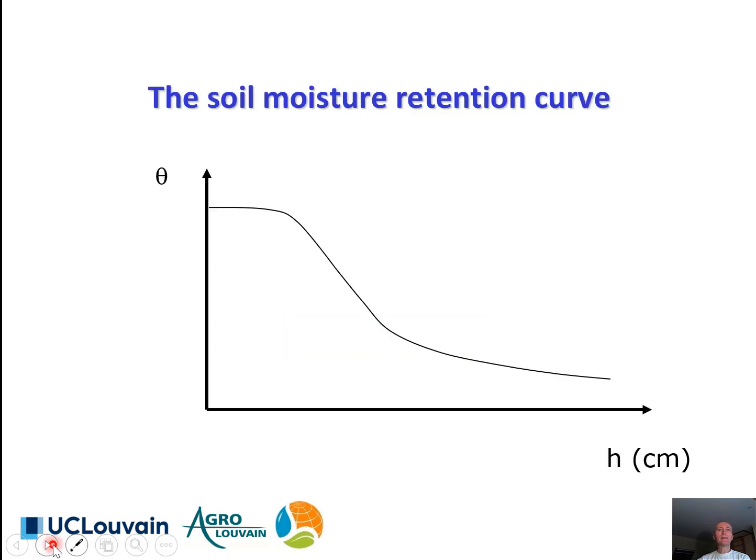The specific link that exists between capillary head, or the matrix suction head, and water content can be encoded in the so-called soil water retention curve. Indeed, when soil is not saturated, capillary forces will retain water in the porous medium, and extra energy, extra pressure needs to be introduced to extract this water. The curve is also often referred to as the soil drainage curve or the soil pF curve. It is a nonlinear curve and very soil specific.